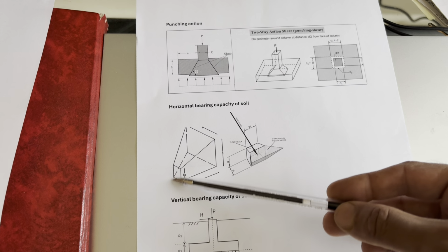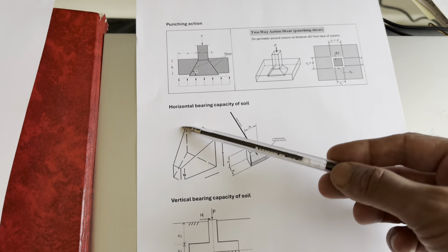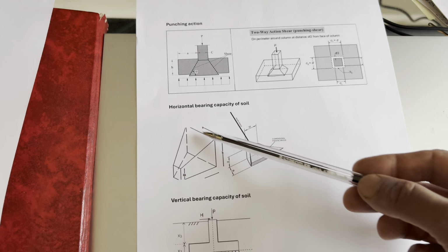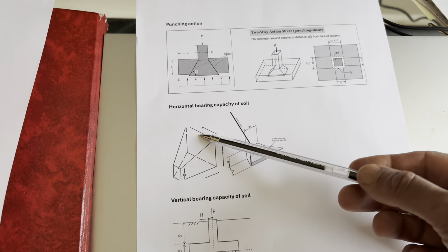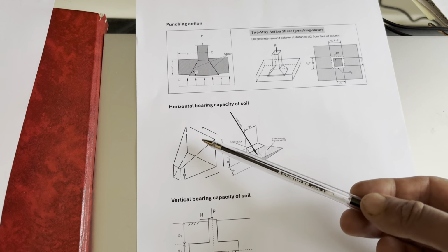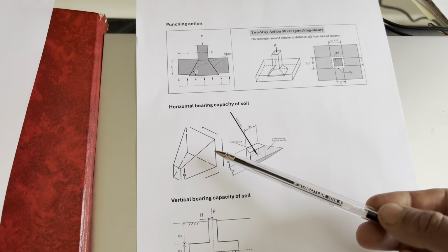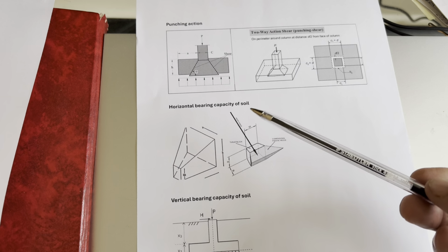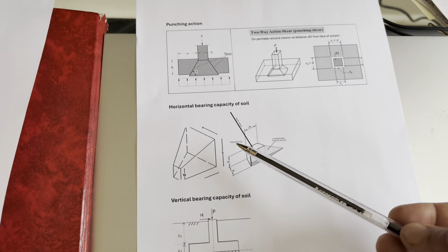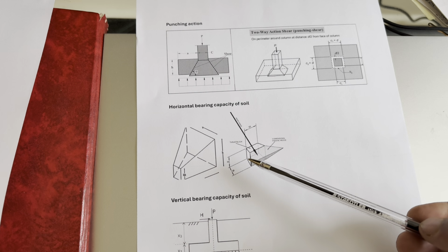So if we have a 200 kN thrust load applied on this area, and the distributed pressure is under 50 kPa, we are safe for the thrust block area. Otherwise, we need to increase the area of this one, or we need to strengthen the soil to have higher bearing capacity. And the next question is, do we need reinforcement for this one?